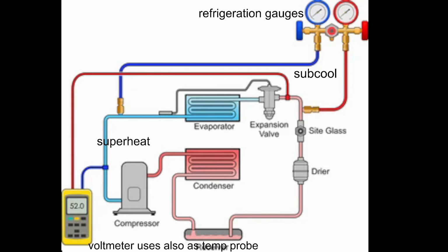If you grab it and feel it on the high side, it's exposed and it's warm. The one for the suction side, you'll have this little black armaflex. It looks like a little black tubing that's around it. That goes around it to keep the cooling effect in the tubing. You don't want that releasing out to the atmosphere, because then your system won't cycle or cool properly. So it'll have armaflex on it. And that's how you'll know that that is your low side of your refrigeration system.